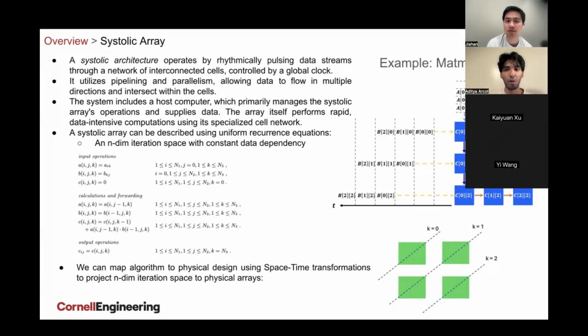So now to improve upon the baseline implementation, we developed a systolic architecture, which consists of data streams that push in the row and column data to multiple PEs at the same time. And these PEs are used to calculate the result of that index for the output matrix.